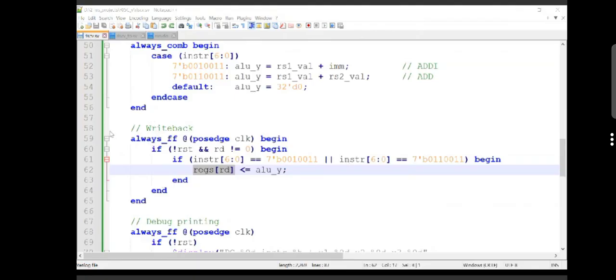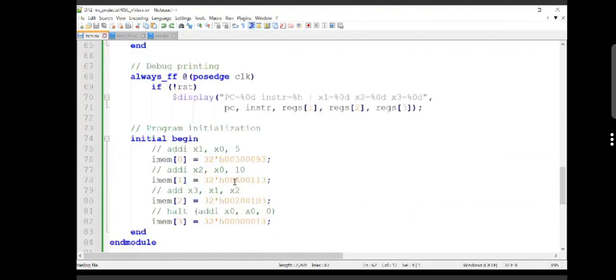Yeah. See here, in this it is filtering your source 1 and source 2. From this data only it will filter. So for the first one, whenever your clock is positive edge and whenever your reset is 1, even if you are giving any data, your PC value is 0. So if you are giving any data also, you don't get anything itself. Your register values will be 0.